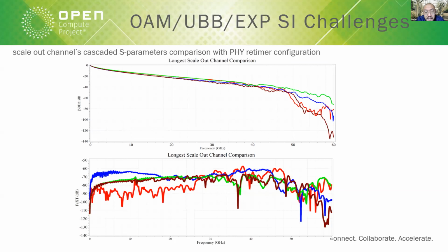However, you can see the insertion loss after 50 gigahertz has some discrepancies. Some of them have a worse cutoff. Some of them have pretty good linearity all the way to 60 gigahertz, right? That's dominated by the OD connector that we use from the 4 different participants. So different board-to-board connectors, orthogonal connectors, have different cutoff frequency performance based on their design.